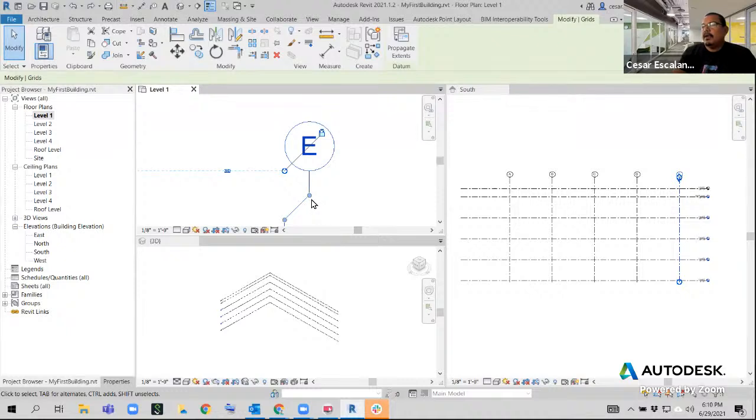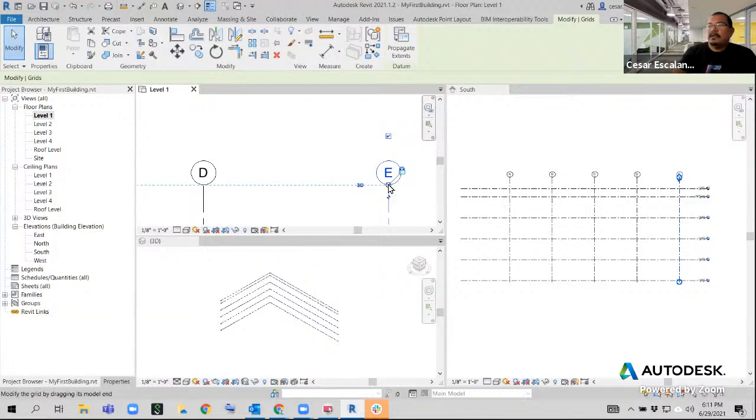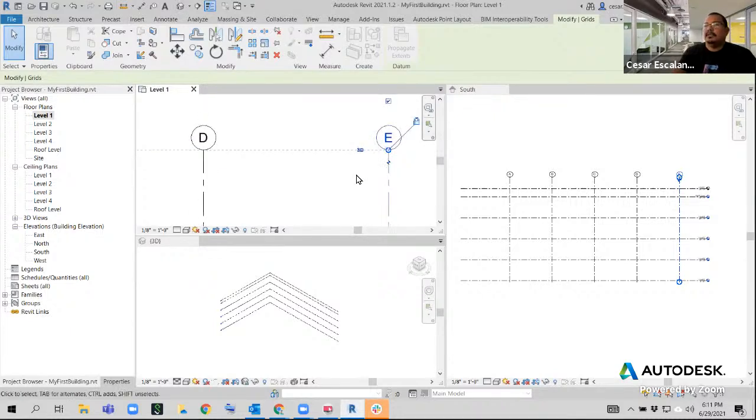To heal them back to the previous location, you just drag the grips and align them. You're going to feel that they snap and then they're going to heal. It has this little lock that is a visual clue that these have an alignment constraint. If you grab the grip from the end point, you will move all the locked relationships in a single step.